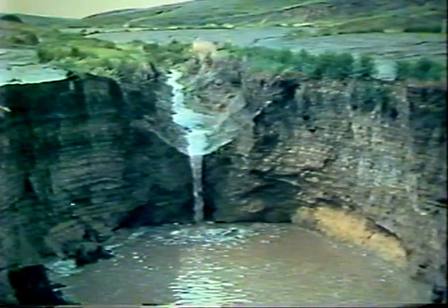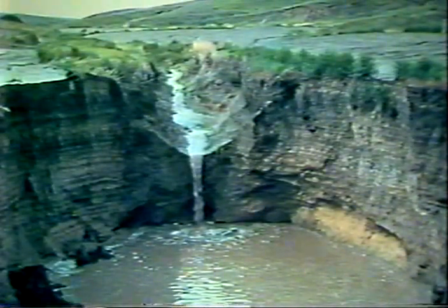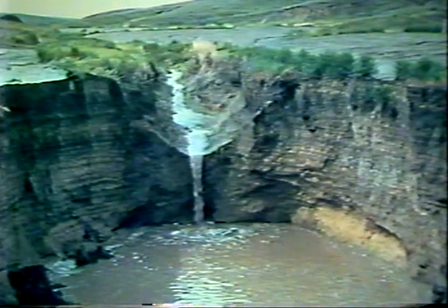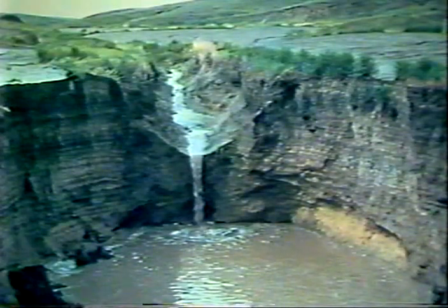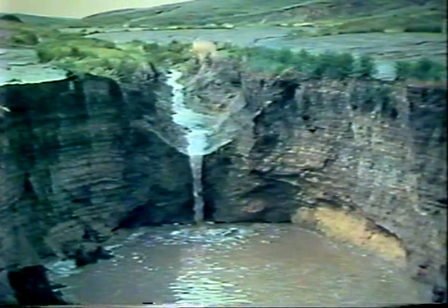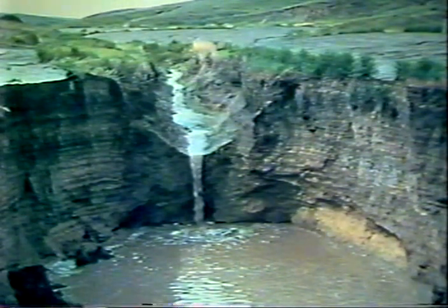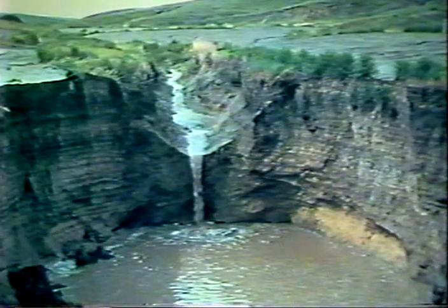On many ephemeral streams, particularly in the Great Plains and Rocky Mountain regions, channel degradation takes place by the upstream migration of steep channel scarps or head cuts, like this one in Nebraska. If a major scarp migrates through a bridge waterway, the channel may be degraded by 10 feet or more. At this bridge in Wyoming, a rock and wire mattress has been used to diminish the degradational effect of a head cut at the orange pointer. The mattress extends continuously across the channel bottom from the side slopes.